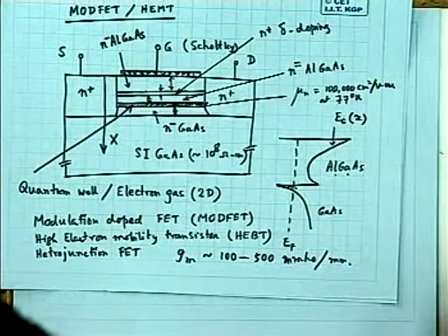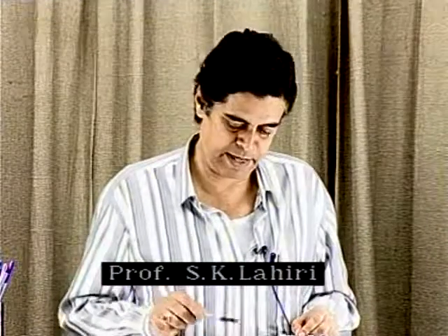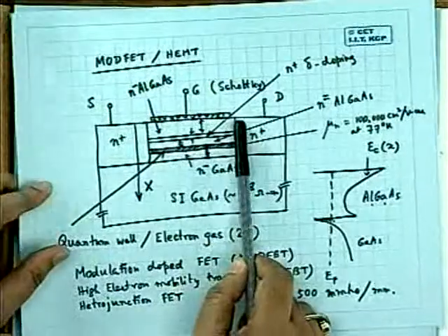This is a basic thing of MOSFET, the very basic MOSFET structure. The speed can be very, very high. It can easily go down to the range of tens of picosecond, and the gain is also very, very high. As a result, gain bandwidth product of such devices is very large compared to ordinary devices for the same feature size. That's the advantage.